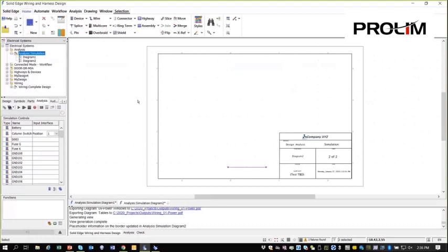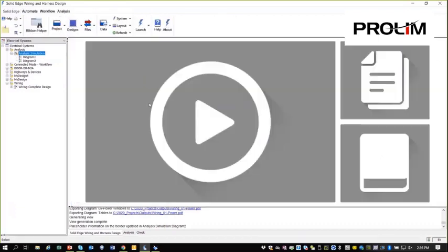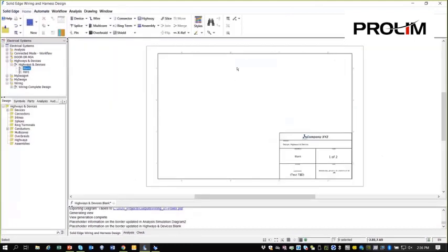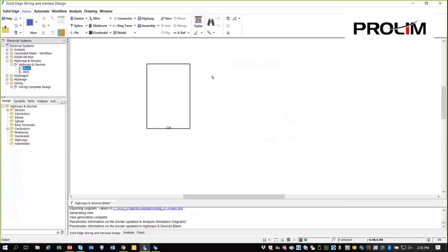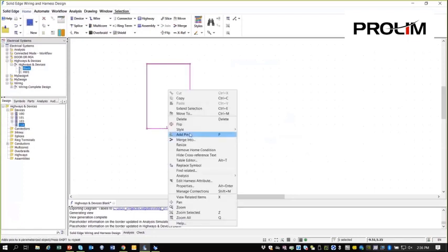So with that, I want to show devices. And devices are used when you want to be really flexible. I've showed you when we're using symbols, when we're using parts. If we look at devices, these are helpful when you're drawing and capturing your schematic, right, and you don't have the symbol or the part built yet. And so I can come up here and say, I just want to put down a device, and I'll add details later to it. There's no pins on it. There's lots of different ways to put pins on. I'll show you a few of them.